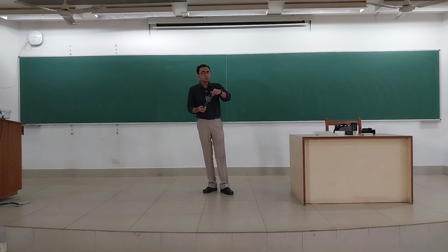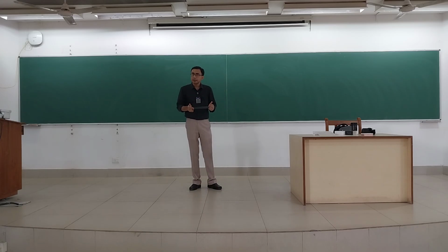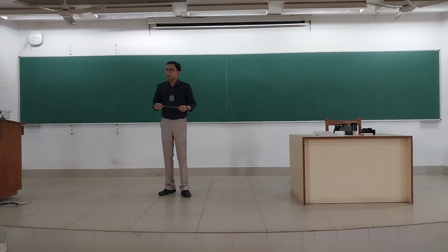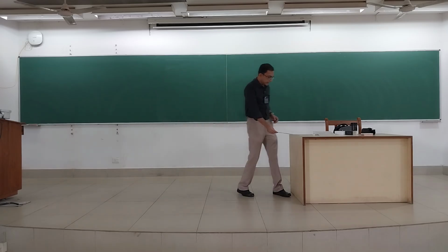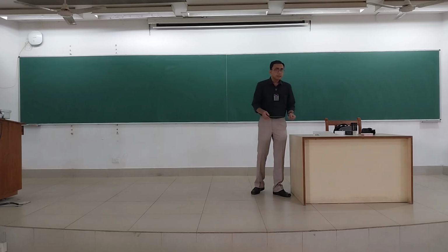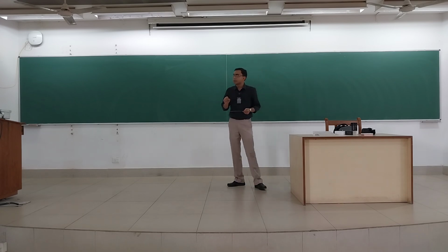Now please note that this kind of a deflection that you are seeing, it is certainly bending. There is no doubt about it. But this bending is a little bit different from the kind of bending that we have learnt earlier. Meaning that what I have over here, if I just press down here, what is this? This is a cantilever beam, right? Here, the load is actually transverse in direction to the longitudinal axis of the beam. So there is actually a transverse load which is inducing the bending.